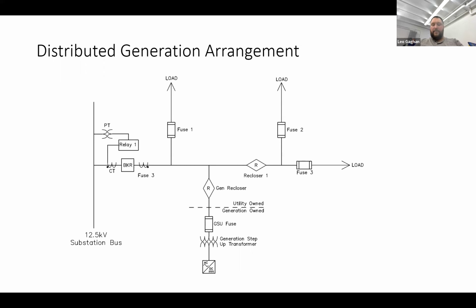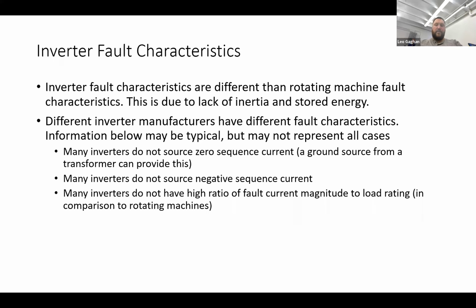We got a way around that. The one that's becoming a much bigger deal, the fact that they also can't source a negative sequence current. Putting a ground source out on that distribution circuit is not going to help with that problem.